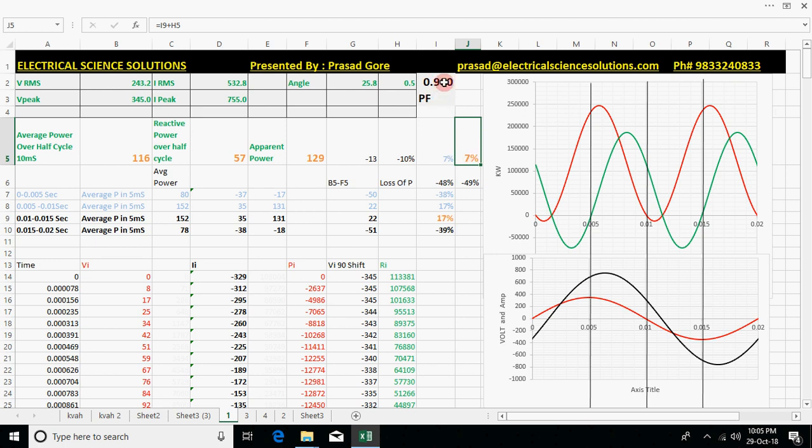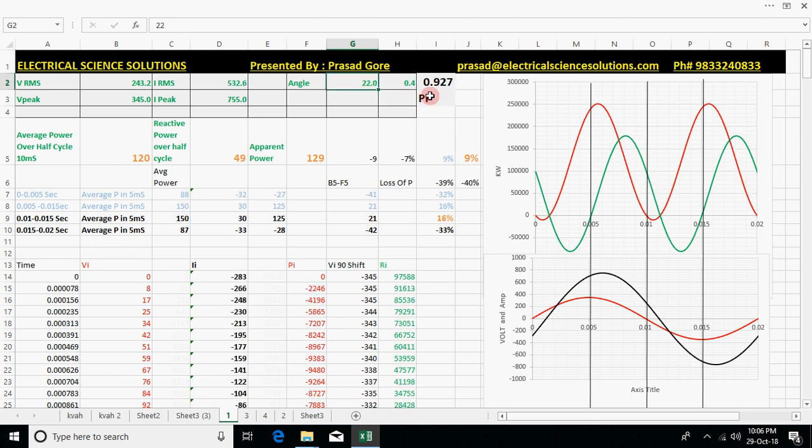Now, why after 0.95, if you maintain a power factor 0.91, they don't offer you any incentive still? Let's understand the reason. Let's say you are maintaining 0.92. What happens? You are underutilizing by 7%. Here you are overutilizing by 6%. So you are released 3%, but still you are utilizing an extra 6% here. So they just don't want to give you any incentives at this.